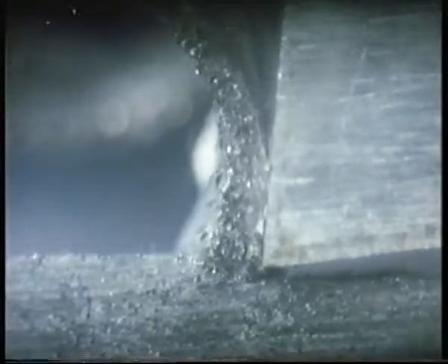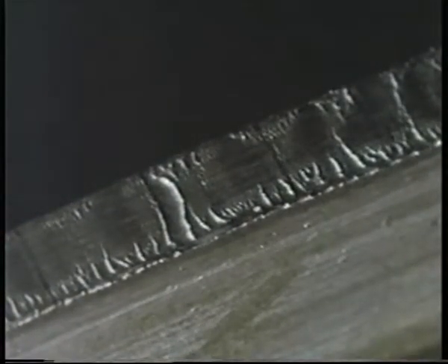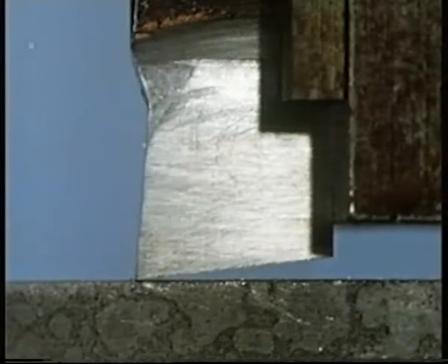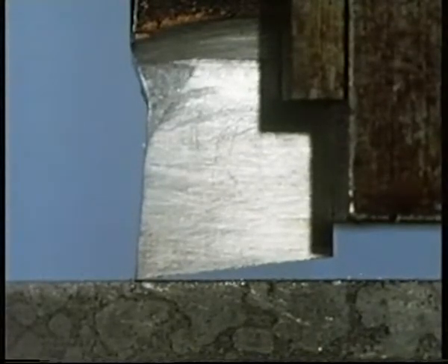Now, if you look carefully, you'll notice that the position of the shear plane is changing. And look at the material building up at the cutting edge. This disturbs the way the chip flows and will affect the surface finish. Remember, this surface is the result of giving the tool a 5-degree rake angle. What happens if we increase the rake angle to 15 degrees?